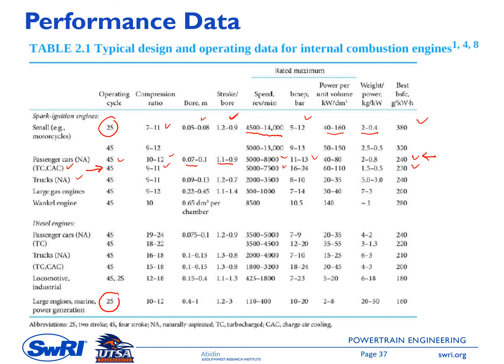This is for a truck without turbocharger. It now has a higher PSFC. And the next one here is for a large gas engine. So it is 4-stroke, and the compression ratio is 9 to 12. Right now we are doing research on this large gas engine, looking at slightly higher compression ratio, but we are still doing this research, and we are testing the engine now on whether it creates NOx or not. And then this is the typical bore and stroke to bore ratio.